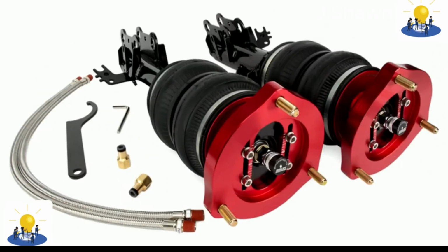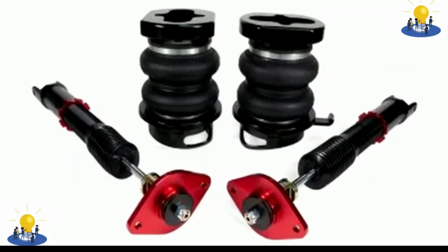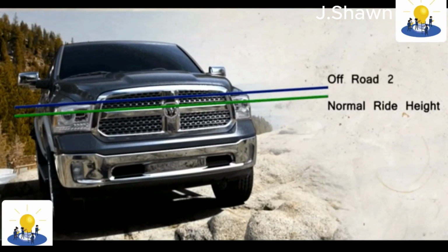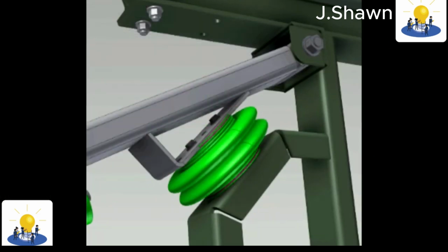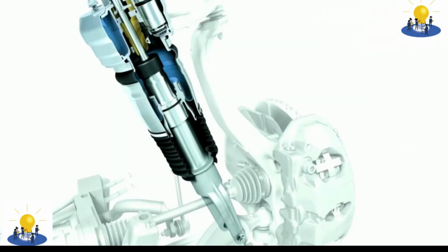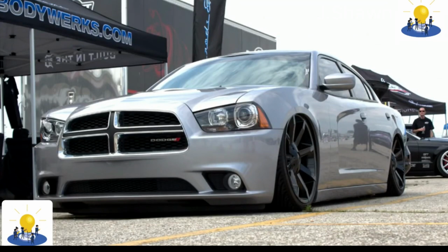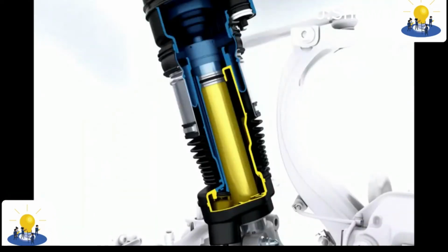Air suspension is also a common suspension upgrade for those who tow or haul heavy loads with their pickup truck, SUV, van, or car. Air springs, also called air helper springs, are placed on existing suspension components on the rear or front of the vehicle in order to increase the load capacity. One of the advantages of using air suspension as a load support enhancement is the air springs can be deflated when not towing or hauling, and therefore maintaining the factory ride quality.